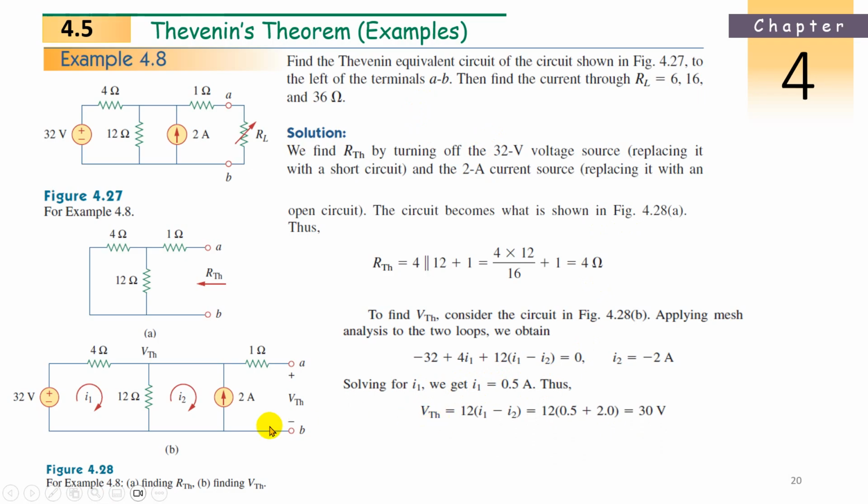Now what is the Thevenin voltage? The Thevenin voltage at the points A and B is nothing but, you have two options here. We can have two options. That is this one. This point voltage is equal to this point voltage. Why? Because in this resistance, is any current flowing? Anyone? Is there any current flowing in this 1 ohm resistance? It's in series, I know. After this parallel, it becomes series. But will any current flow?